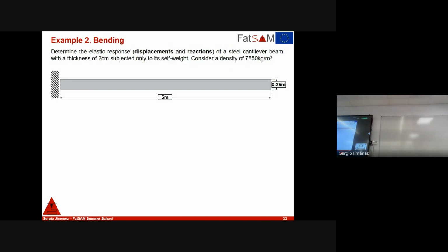Actually, it's already created. Here, this is the part in which the groups that you create using this boundary condition, material properties, nodes, and so on, appear. Here, what you can do is double check that everything coincides with the information that you really want.